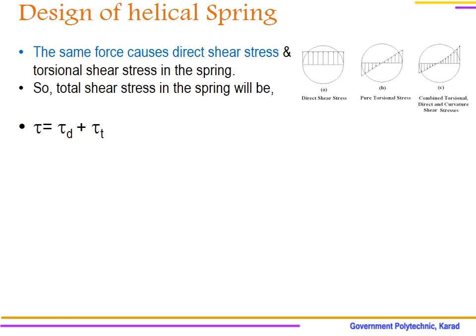So when you imagine that the wire is rotating, its surface will be displaced more. The center will not be displaced. Means at the axis, at the center, stress is 0 and at the surface stress will be maximum. So stress is increasing from the center to one side of the surface. So likewise is the distribution. Stress is not uniformly distributed. Both stresses we are adding here.